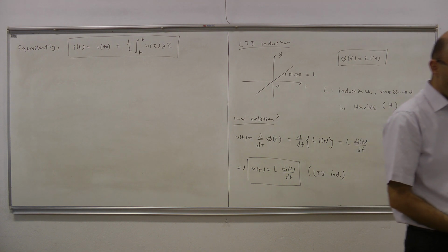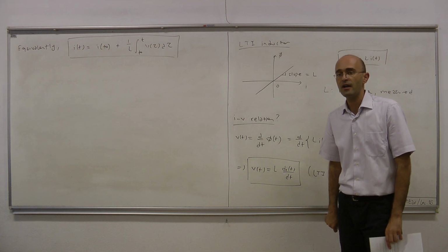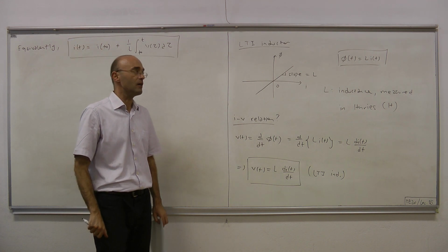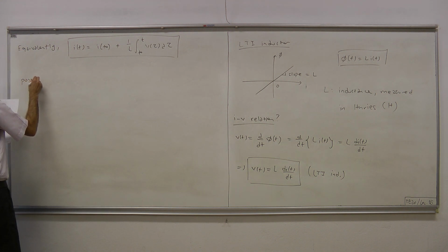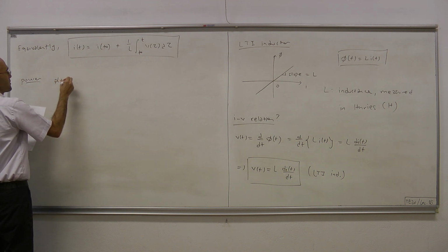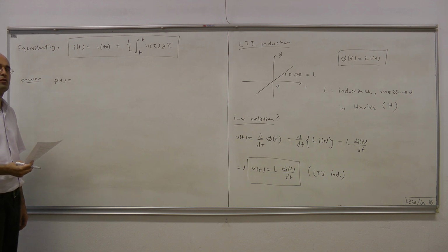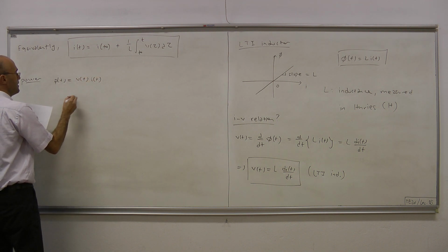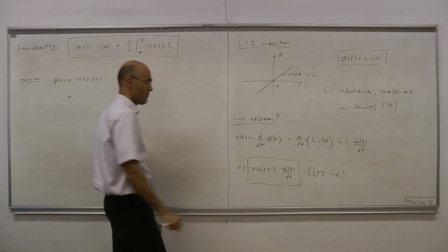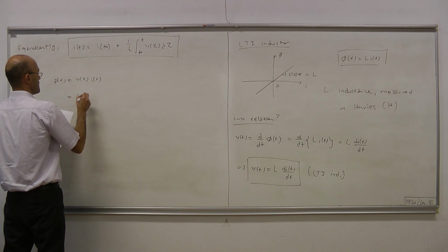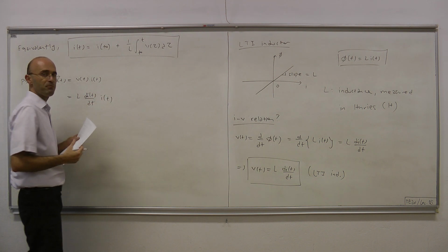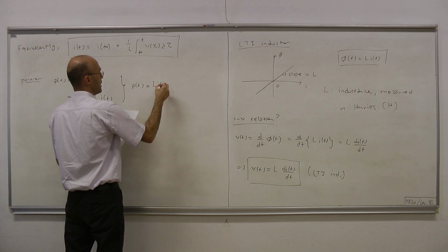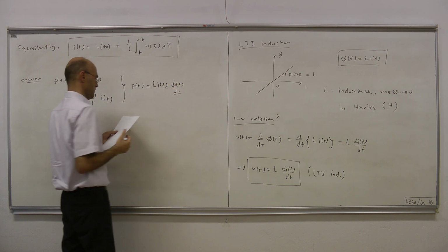Now let's also talk about power, and more importantly, the stored energy for an LTI inductor, and then we can summarize what we have seen for our LTI components altogether: LTI resistor, LTI capacitor, and LTI inductor. So power for an LTI inductor goes as follows. We start from the general definition of power of a two-terminal component, which is the product of voltage and current, V of t times I of t. And then we replace the voltage by its description, L di/dt. So that gives us L di/dt times i(t). Therefore, the power at any given time equals L i(t) times di/dt.